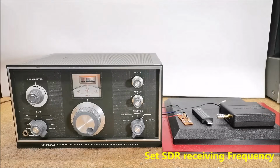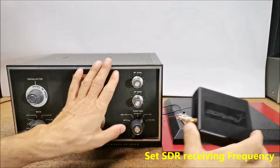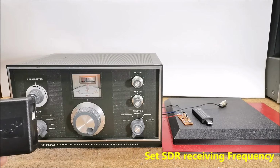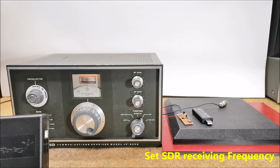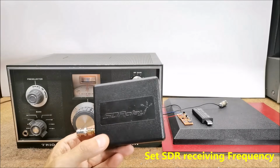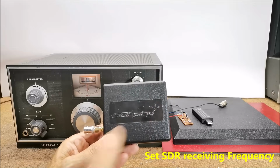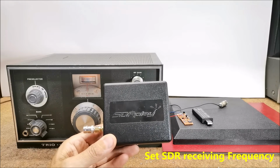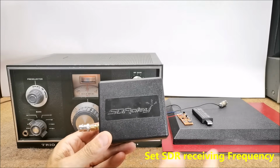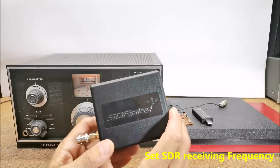The SDR receiver needs to be able to handle the intermediate frequency from your radio. My Trio JR-500S has a 9 MHz intermediate frequency, but your radio may differ. It's important to notice that the frequency on your SDR receiver will be centered around the IF, in my case 9 MHz, which is no problem for my SDRplay.